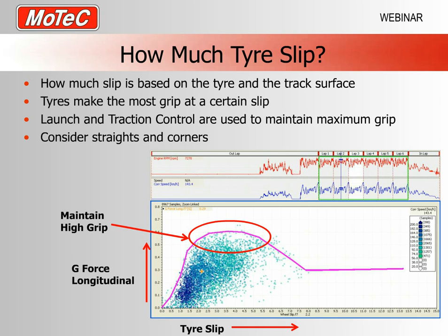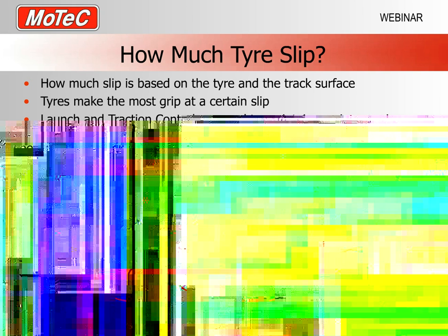So the smart guys will be thinking, what can we compare slip to make sure we are using these tyres at their maximum grip. I can guarantee that in a corner you are going to get away with a lot less slip to accelerate the car than if you were in a straight line. So this is what you have to be looking for these days, and it makes a big difference on a circuit car, that's for sure.